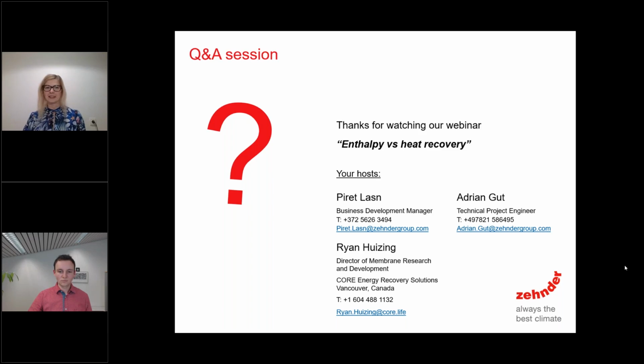Yes, there's one question. Are the condensation pipes still needed for ventilation units or not? For the HRV, you still need a condensation pipe. For the ERV, you do not need a condensation drain. That would be the answer for this question.